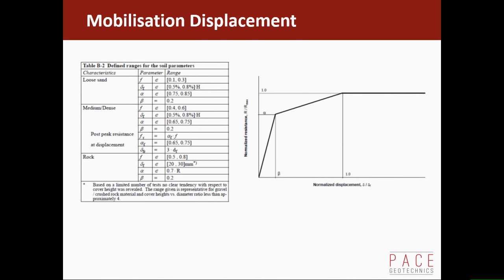So if your full mobilization displacement is your ultimate resistance from the previous equation with the gamma dashed, and the 0.8 times the that, in that range there is where sort of 75 to 80% of your total ultimate resistance will be achieved within 0.2 times the maximum displacement, to a sort of plastic failure of the soil around the pipeline, the ultimate resistance that you get.